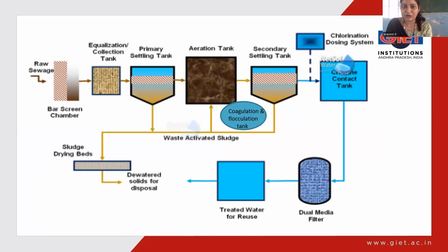So this is the outline of a wastewater treatment plant. There are different units. Each tank has a specific function or specific role to play. So at every particular tank, at every particular unit, some impurity is getting removed. Here, as I've just told you, there is primary treatment, secondary treatment, and tertiary treatment. Initially, primary treatment. What happens in primary treatment is mostly usage of screens. The screens are going to remove the larger particles from the wastewater.